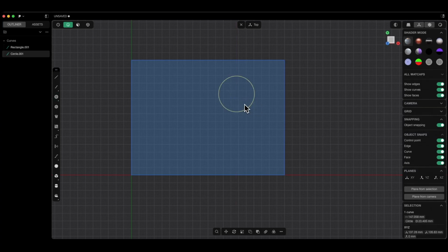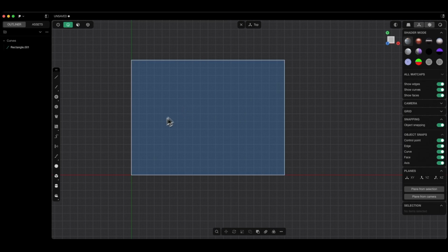Now, regarding creating precise shapes, as you can see, when I draw some geometry, I tend to place it quite freely without defining its position. In typical technical 3D CAD systems, when drawing, for example, a circle, I can also define its position relative to some other geometry. I can define relationships between geometries. In Plasticity, we don't have that in the same way as in parametric CAD, although we can still add dimensions between geometries and later modify those dimensions. We'll get to that shortly, but first I want to show you some ways we can handle creating such geometry.